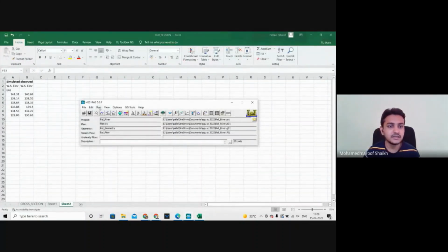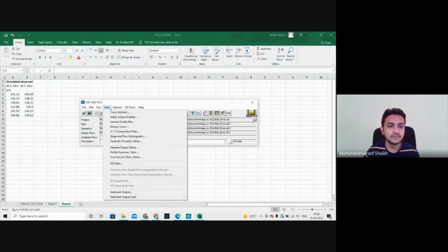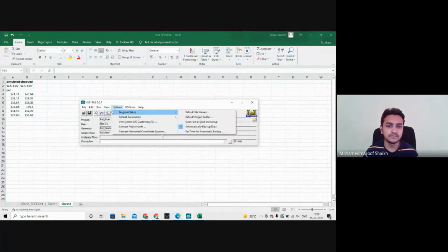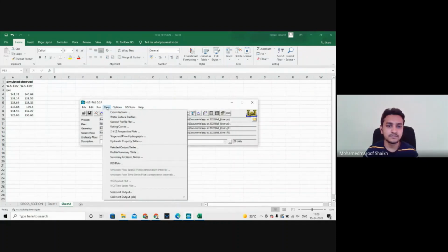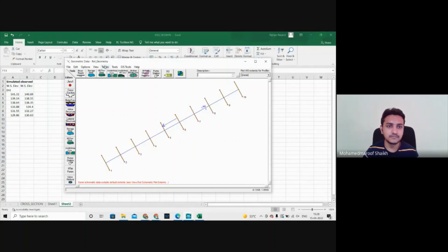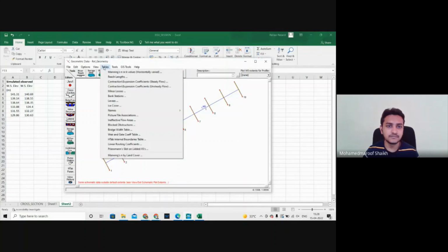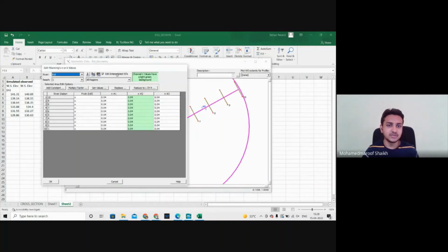So again, for that, go to geometry data, tables, and Manning's n values. Here we will change our Manning's value.